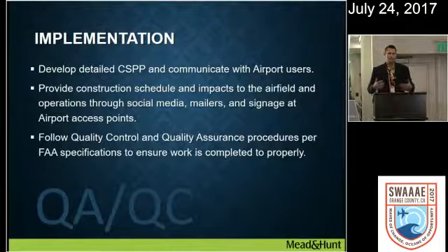is that when you do the marking removal, drum grinders work extremely well on non-grooved surfaces. Water blasting is also an option. But when you get on the grooved runway surfaces and you have to relocate markings, it is a very big challenge to be able to remove that marking effectively and not have that shadowing or ghost markings after, without having to replace the asphalt, which the water blasting really does a detriment to those grooves.